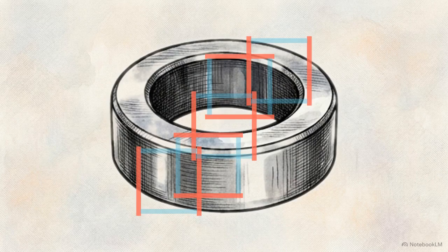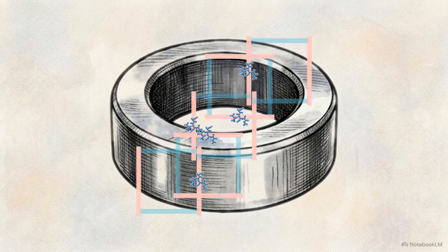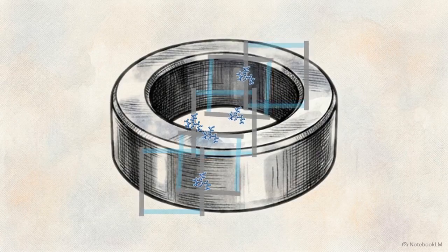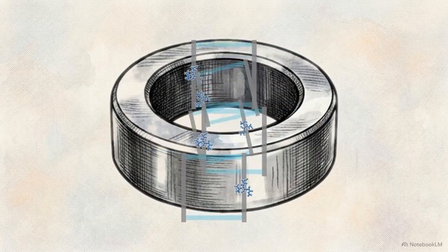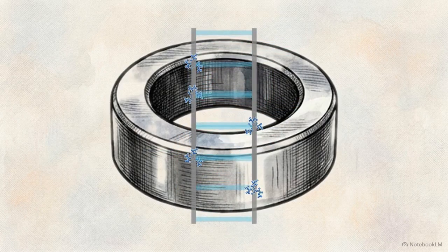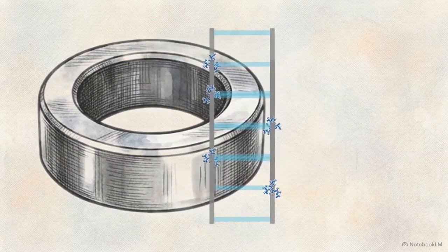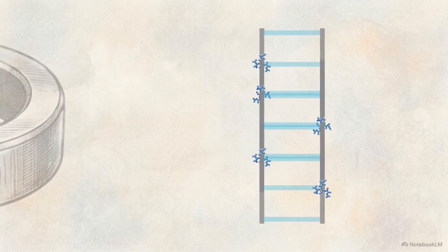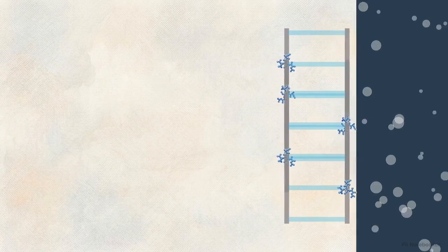They function as highly powerful anionic, or negatively charged, dispersants. Watch as they enter the matrix and specifically attach to the positive edges of the clay plates. The strong negative charge of the thinner completely neutralizes the positive charge along those thin edges. Without the positive edge attraction, the edge-to-face bonds can no longer hold. The plates repel each other and break apart, physically destroying the flocculated brush heap structure. As a result, the yield point drops, restoring normal fluid flow.